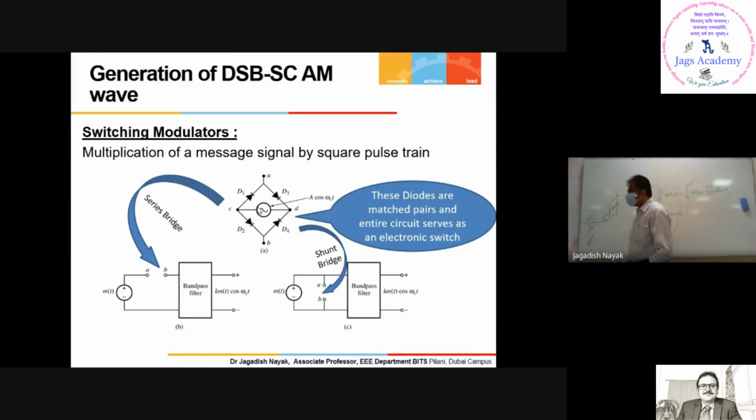Band pass filter, you don't know? Come on, listen. A band pass filter passes a certain range of frequencies, and it removes all the other frequency components in the signal. That's called a band pass filter. Exactly. See, in this, we want only omega c, right? We don't want 3 omega c. Remove all the components and keep only omega c. Now, have you understood the requirement of signals and systems here?